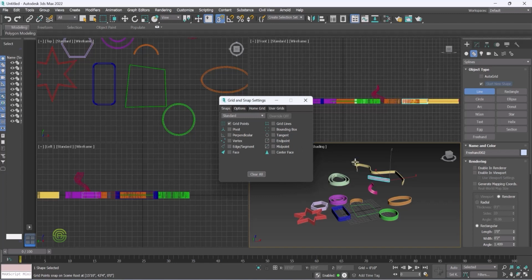When you import a CAD file, AutoCAD file, at that time we have to check on this vertex so that we can click on the points on the CAD plan, and then we can trace the wall. Then we can convert it to wall. So by using line, we can create wall by tracing the AutoCAD plan.